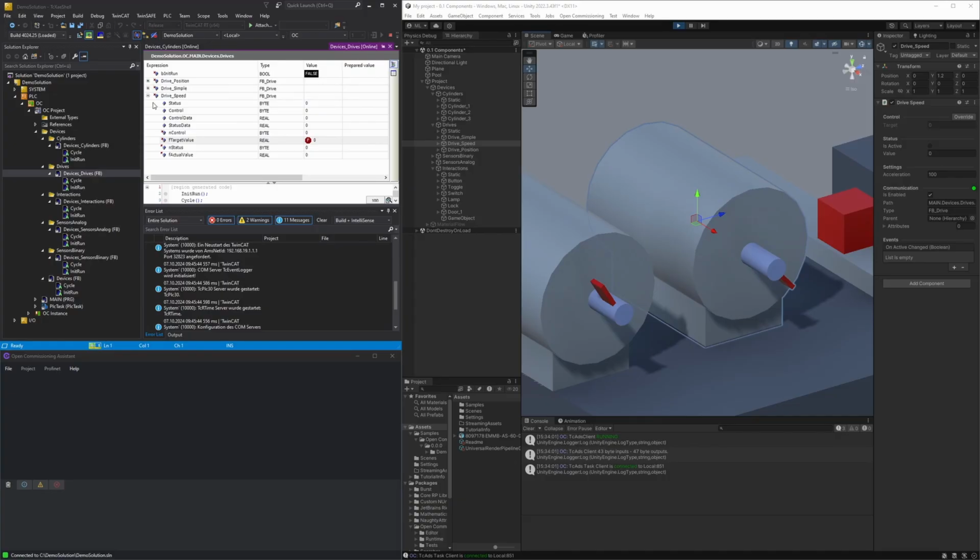This was to show the automatic generation of the project and generally how the Unity simulation is connected to the TwinCAT behavior models. Of course, in a regular virtual commissioning project, you don't force values by hand. You use a PLC program to write those values.